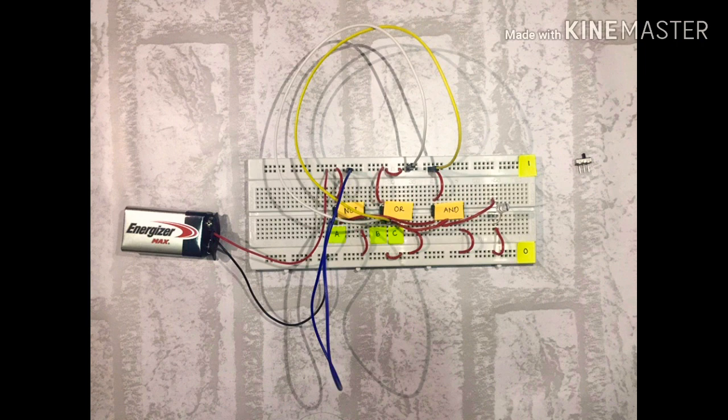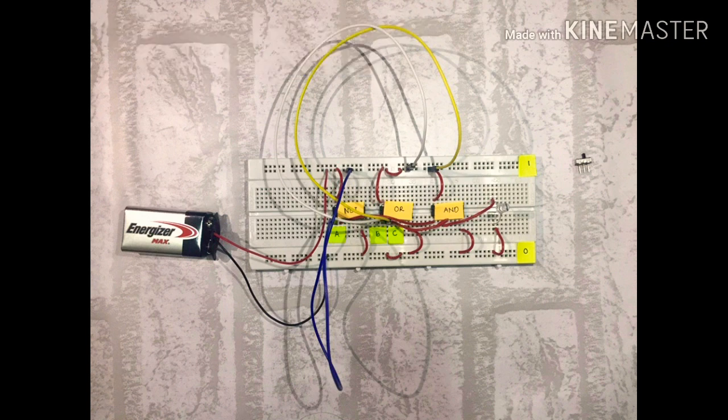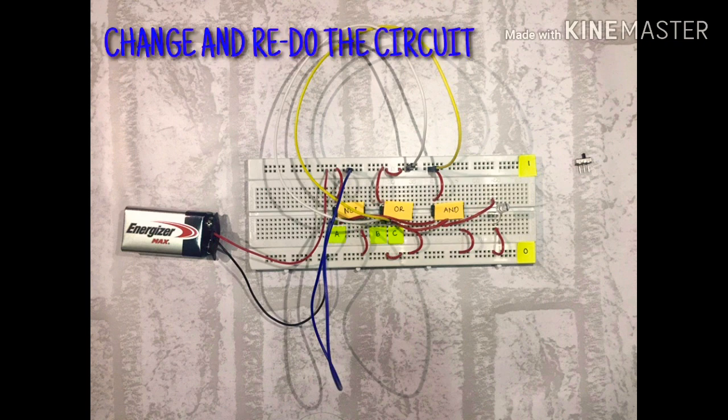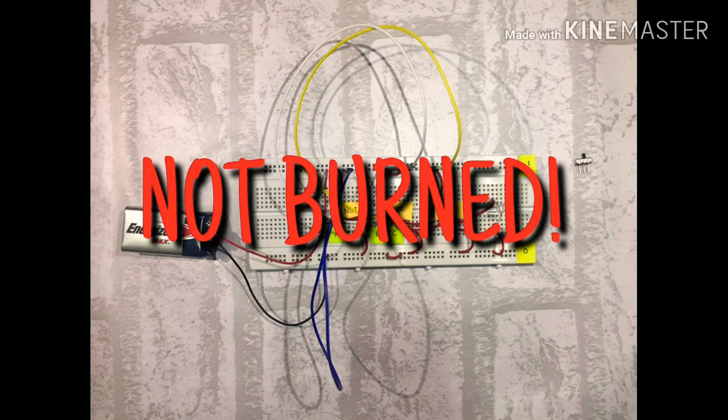While setting up this circuit, we went through a few problems. The worst problem was when the multicolor LED lit up, but did not follow the truth table when we switched the switch on and off. We tried to figure out the solution by changing and redoing the circuit a few times. We thought the IC or LED had burned out during the project, but when we tested the IC by connecting it from the battery to the LED, it went fine.